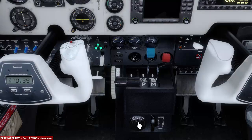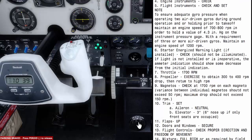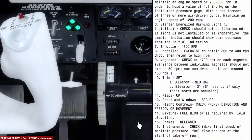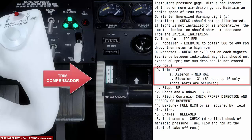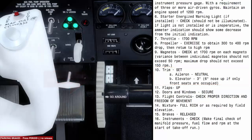And very soon we will configure the elevator trim to the 3 position or 6 position, and that is basically what I am showing you there, how to configure the elevator trim. The elevator trim must be configured to 3 degrees, or to 6 degrees if only front seats are occupied. I will configure it with 3 degrees. I feel comfortable with that setup, and I assume I am flying this aircraft alone.